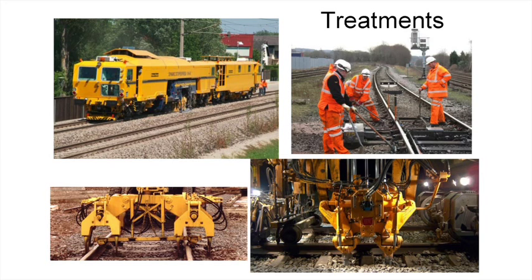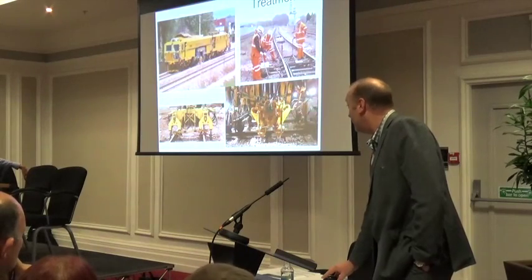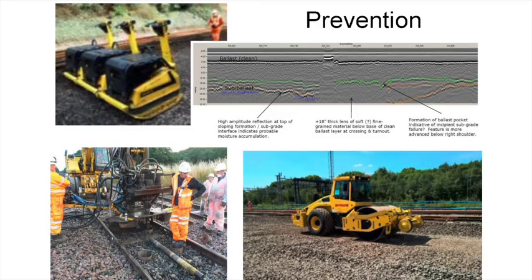The railway spent a huge amount of time and effort treating problems, but probably not curing them, not permanently. So anything, stone blowers, tampers, all sorts of hand techniques. Peter's touched on some of them. We could do a bit more, perhaps compaction of formation, localised interventions with micropiling and similar. Some of the other equipment that's used widely in other parts of the industry, certainly construction of road and similar, with much larger rollers, more effective compaction, better use of data as well.